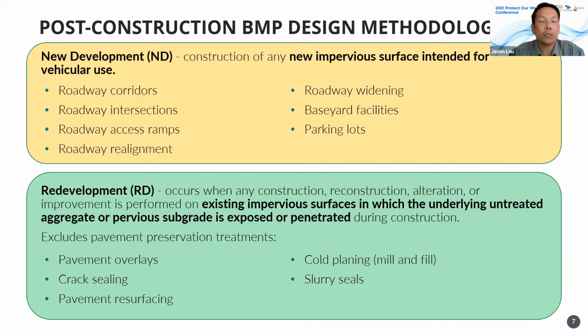Okay, so sizing these post-construction BMPs is based upon the new development and the redevelopment that's included within your project. New development is defined as any new impervious surface intended for vehicular use. The last part of that sentence, for vehicular use, is important, because a bike path or a walkway intended for pedestrians is considered a non-pollutant generator. So those are excluded from the new development area. New development area is just for vehicles, so it includes roads, intersections, parking lots, base yards.